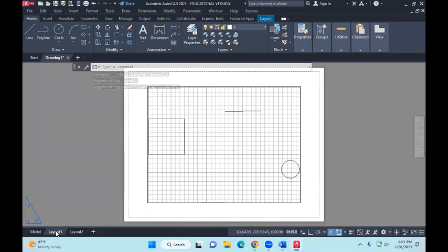Now the layout area, this layout page. Just like in spreadsheets, Microsoft Excel, you can create many pages or many sheets, sheet 1, sheet 2, it keeps going, right? So you can have multiple layouts. Let's say, for example, remember in model space, you can have multiple drawings, like a floor plan, you could have an electrical plan, just saying, right? And it doesn't mean that you need to create new files for each particular plan. If you are doing something really basic, you could have 3 or 4 drawings in the model space. But then it depends on the layout, which particular drawing you would like to display.